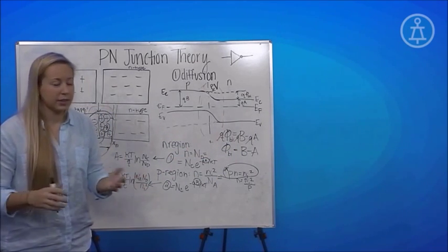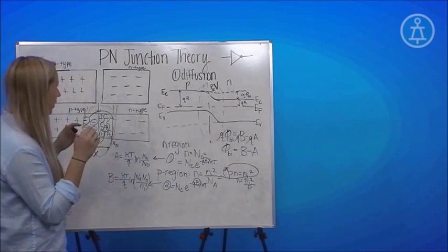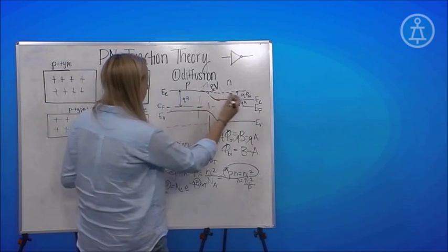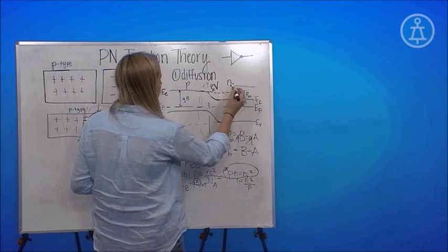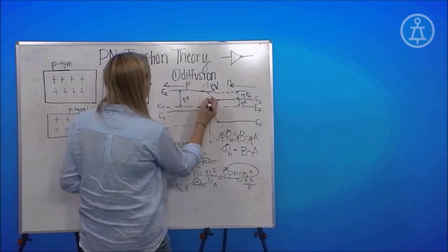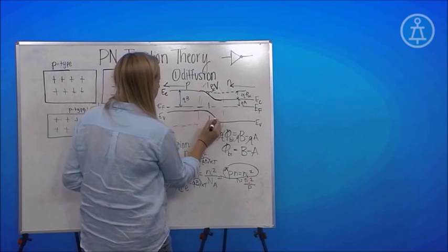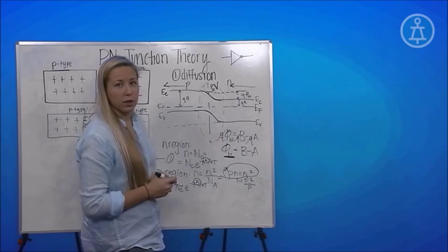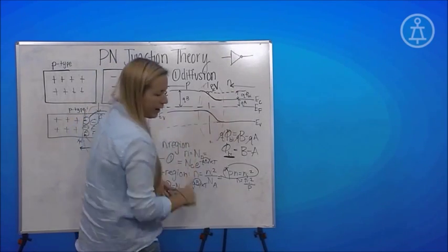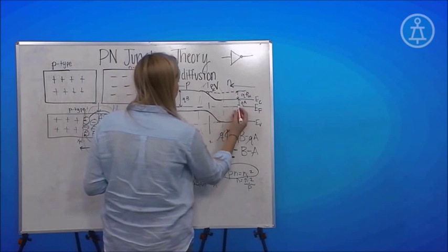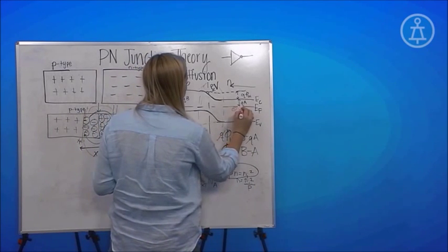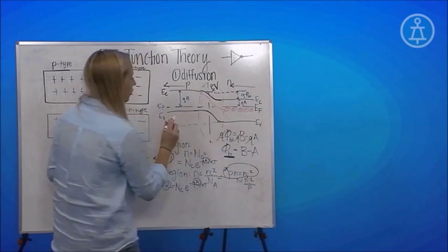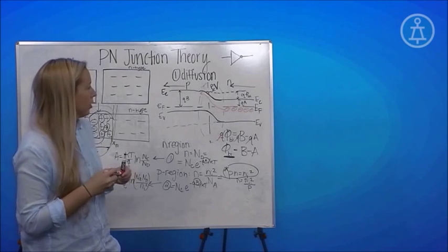And so what's really interesting is if I were to apply a voltage the opposite way, right? I need a big enough voltage, theoretically bigger than the built-in voltage, to have current flowing. Because what happens visually is these electrons need to have a certain energy to climb up this potential difference.